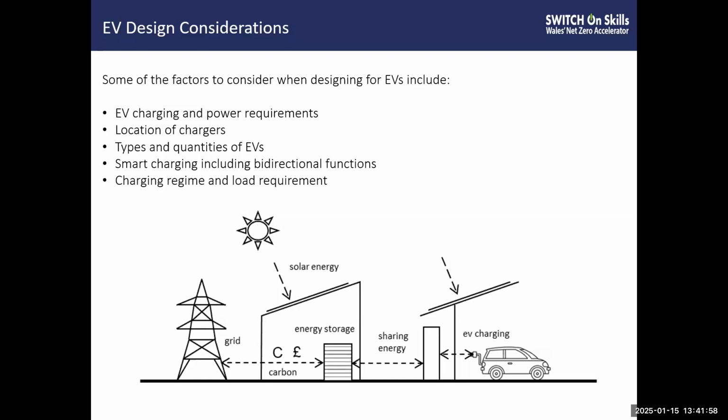And we can also get smart chargers, which can shift the time of day when an EV charges, or to modulate the rate of charge at different times. This allows the building owner to change the speed of charging, or in fact delay the onset of charging based on variables such as demand or carbon intensity of the grid at that time, or as a response to the price, to the cost of that energy. So yeah, it just allows for much better management of the energy.